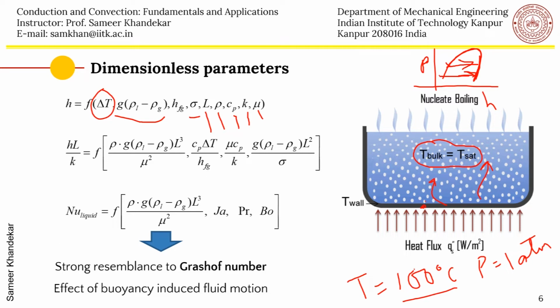So if you apply the Buckingham Pi theorem, you will see that certain non-dimensional numbers come up, which are pretty straightforward. Let's first discuss these four non-dimensional numbers. This Cp delta T by h_fg is the sensible heat divided by the latent heat. This is called the Jacob number. Mu Cp by k is well known.